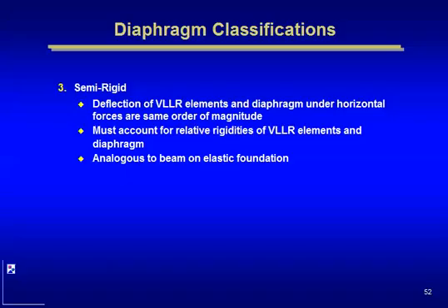And then, of course, there's a whole world of decks that are in between. And as you're going to see, whether it's a rigid diaphragm or a flexible diaphragm may be not only a function of the material, a metal deck or concrete slab, but also the spacing of the vertical lateral load resisting elements plays an important role as to whether a diaphragm is rigid, flexible, or in between, which is semi-rigid.